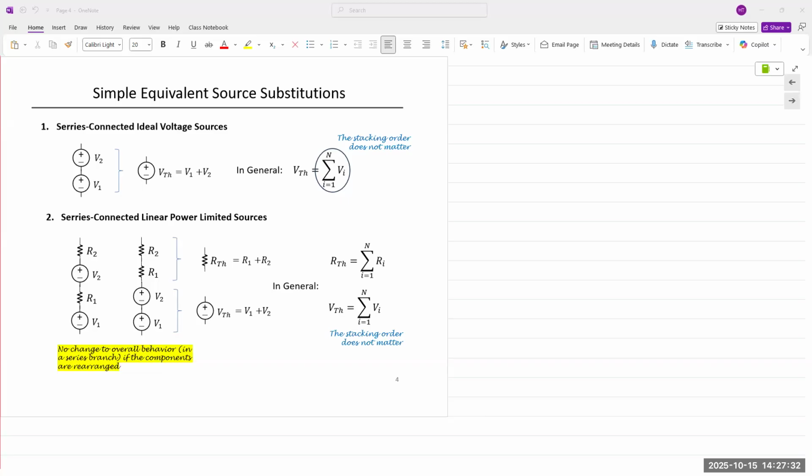Now you keep those two connected at those two points. If you wish to find the Norton current flowing between those two points, what do we need? We need a short circuit. We need a pathway between those two points so that current can flow through. Well, if the meter is still connected and we change the setting to measure current instead of voltage, what does it do?